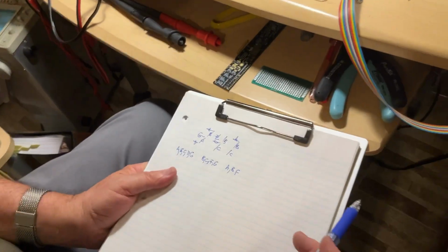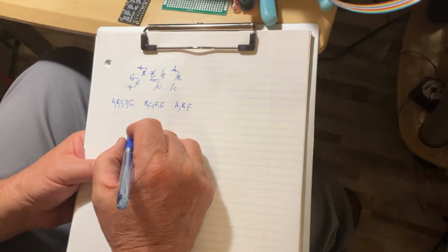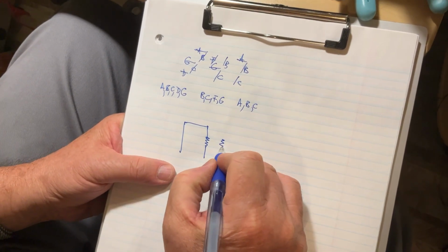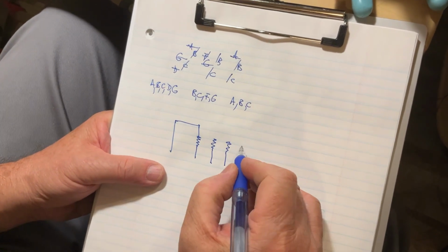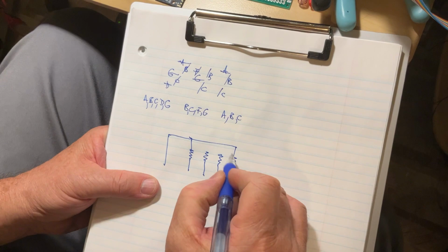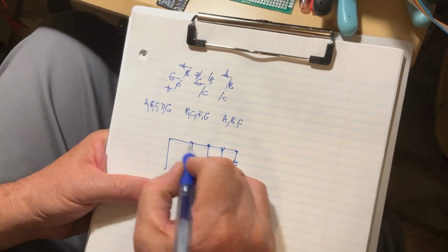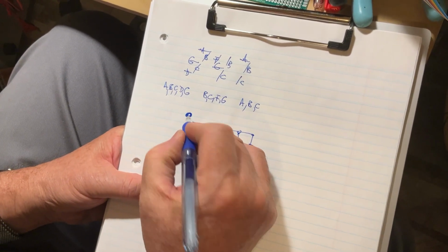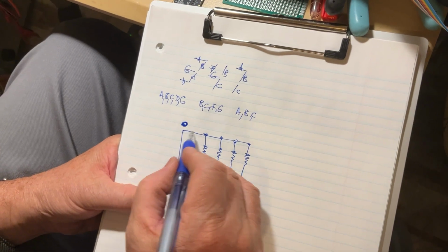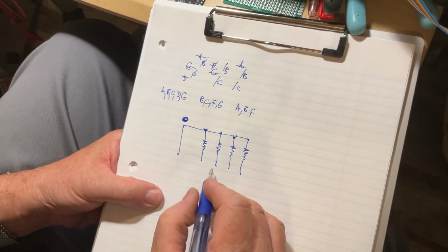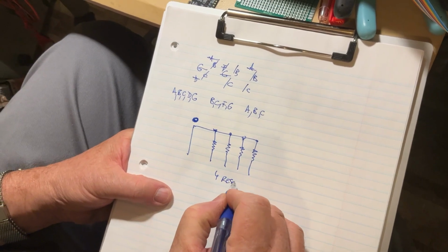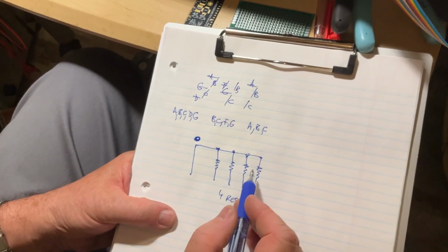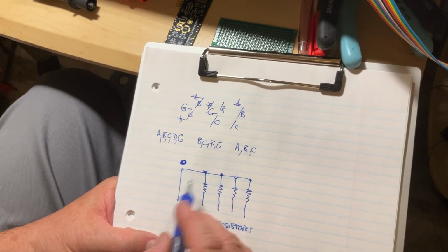I'm going to pick up 2 examples. This one here, the dot is right above the pin common for all the resistors. As you can see, this one, it has 4 resistors. They are arranged like in a network. This is why it's called the network resistor. It's called common bus because they have one terminal related together. This is the common, okay?